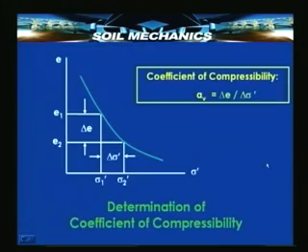Now, we come to a very important parameter, which is what is essentially useful in time rate of settlement calculation. This parameter also defines compression in some ways, but it is different from the compression index in the sense that here we do not make any assumption regarding straight line relationship in a logarithmic plot. We in fact take a relationship directly from the e p or e sigma dash curve.